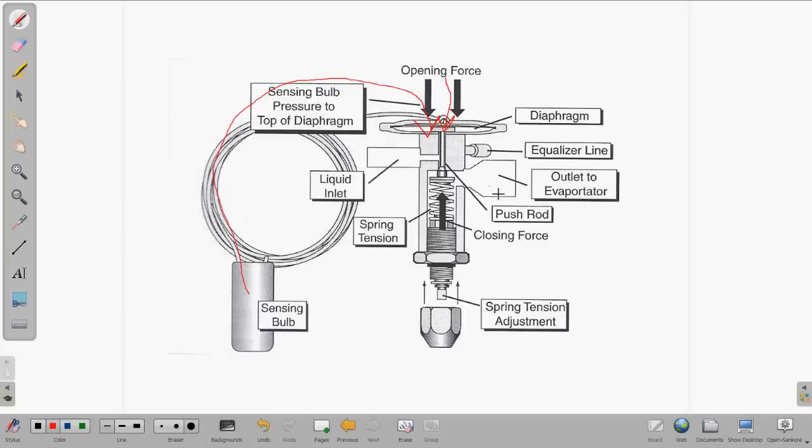So that's your warm and fuzzy. If you suspect a bad TXV, dunk it in the hot water. Make sure that the sensing bulb was pulled out and the cover to the evaporator compartment is closed, and run that system, and you should see that corresponding increase in pressure and changing of pressures on the suction side as that TXV opens and closes.